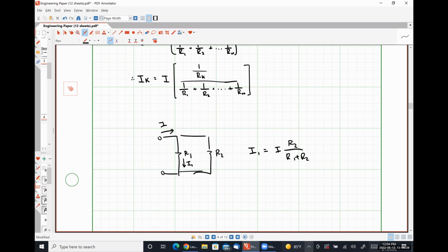Right, for voltage division, that's exactly how it works out. The one you're looking at is the one in the numerator, and all of the things in series are in the denominator. In current division, with 2, very specifically, it works the opposite way. The one that you don't care about is in the numerator, which doesn't make any damn sense to me. Throw that garbage out and learn this. I remember you talking about that in Circuits 1 and warning us about it, but I forgot about that. And then when I look back at my notes, I started doing it that way.